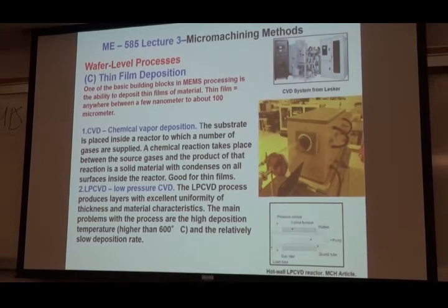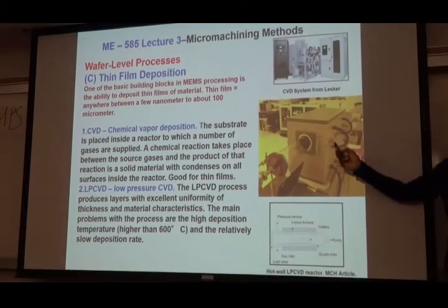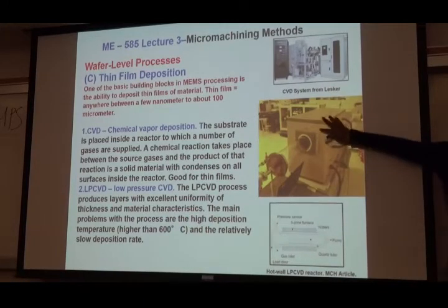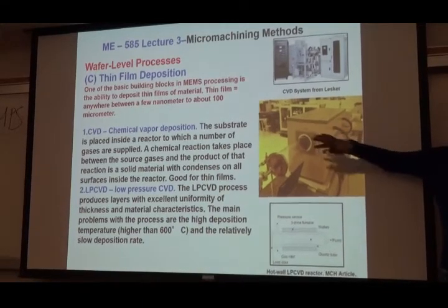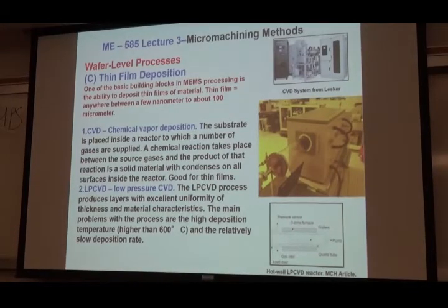I want to heat it so fast, but not heating the whole thing, but by consuming so much energy on this. So essentially what I'm doing with this guy is, for example, when I'm doing CVD, I'm raising it to 1200 degrees Celsius, so I have 50 amps of current coming in, okay? And then this is a heating chamber. Not 6 hours, about 3 hours to reach that kind of temperature. Okay, so it's expensive. From the energy point of view, it's expensive.